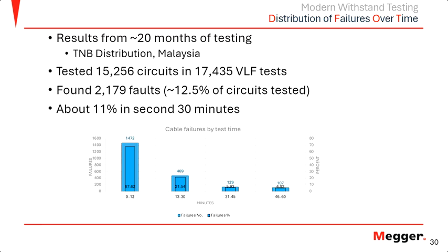So most of the failures that happened were in the 0 to 12-minute mark, and the rest were in the 13 to 30-minute mark. And then it drops down even further when you move from the 31 to 60-minute mark. So that gives you a good idea of how long I should run a VLF test for. So I hope that answers a lot of questions on your regular VLF test.